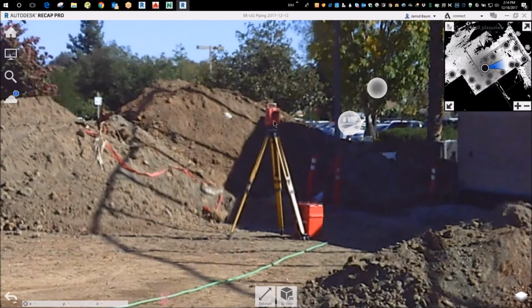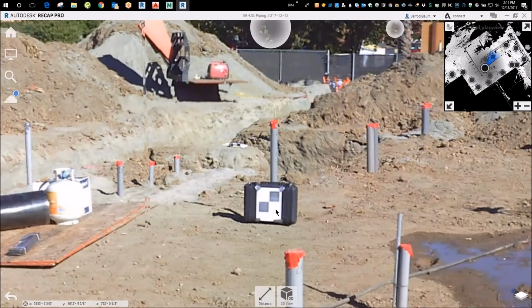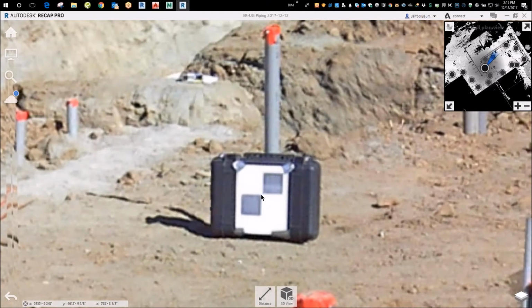So our total station, when set up and synced up to survey control, can then shoot the precise crosshair of that and give us exact coordinates to that, and our scanner recognizes that, and we say that point is this coordinate. And you have to do that with 3 of them so that it has its geospatial relationship, right?